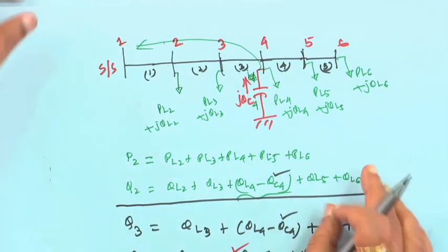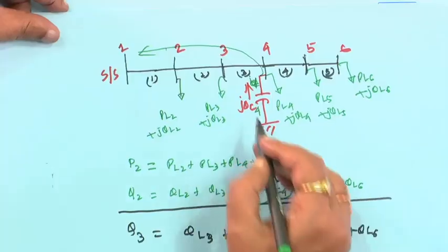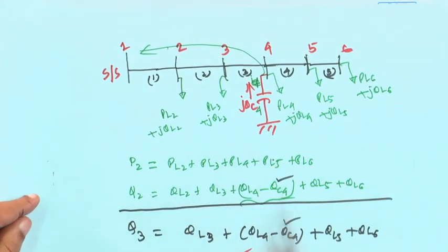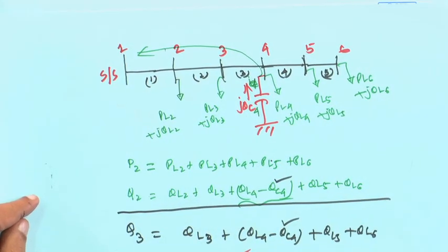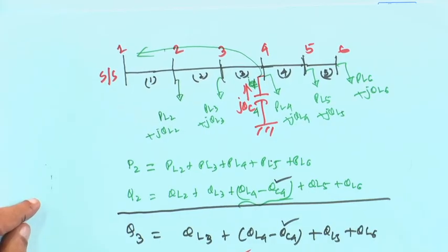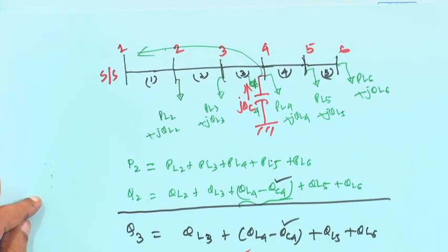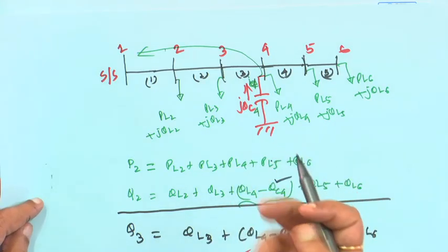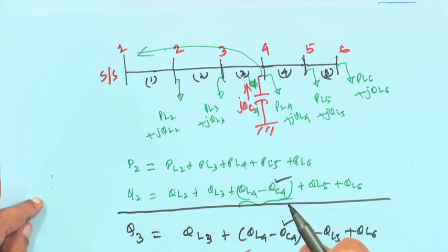So, branch losses will reduce due to capacitor placement when you use a shunt capacitor. The first is the series capacitor, if you put one; we will come to that for capacitor application. The main purpose of a series capacitor is to increase the voltage magnitude at each node. As the voltage is increased, power loss, which is inversely proportional to the square of the voltage magnitude, reduces.